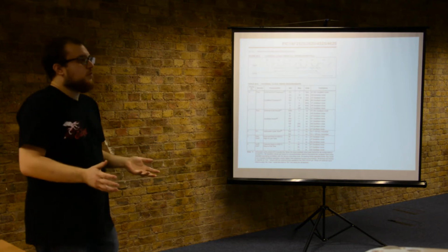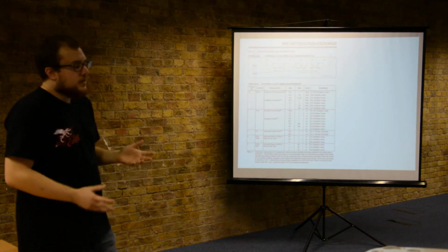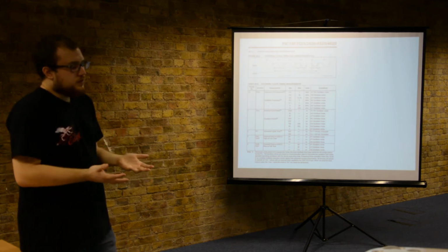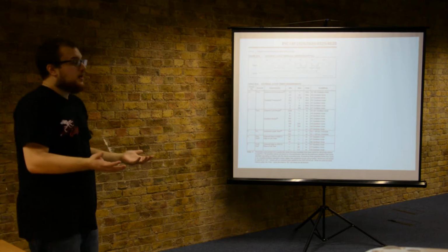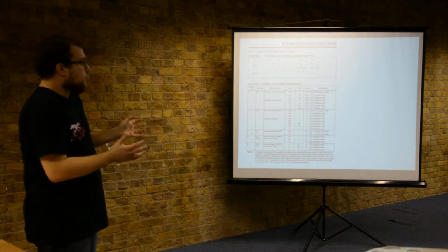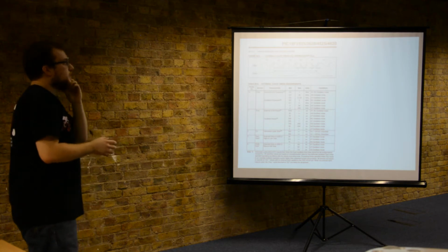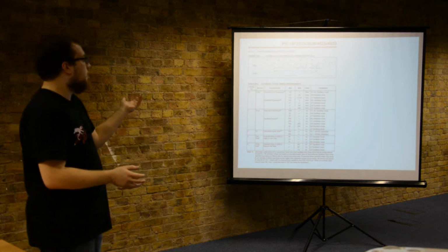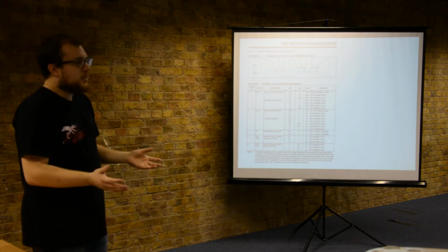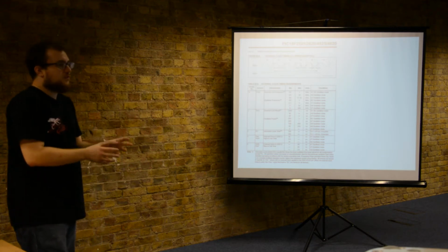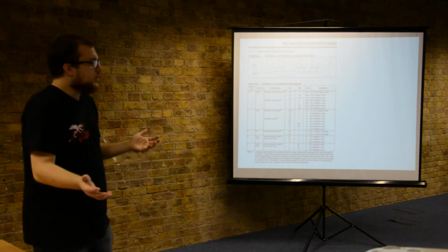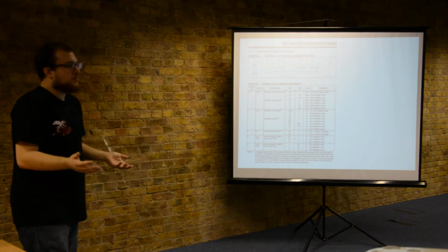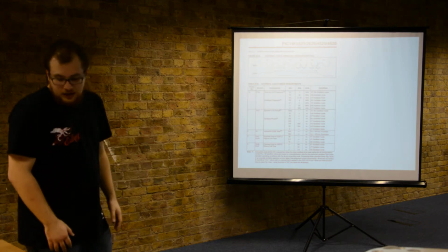uncharted territories almost. What that means is the operation of the microcontroller or the processing device that you use is not guaranteed at those frequencies, but to a certain extent it should be okay pushing them 5 more megahertz. You might find that 2 devices out of 5 would work quite happily at 40 megahertz maybe, but the other 3 might not like going above 25 megahertz.